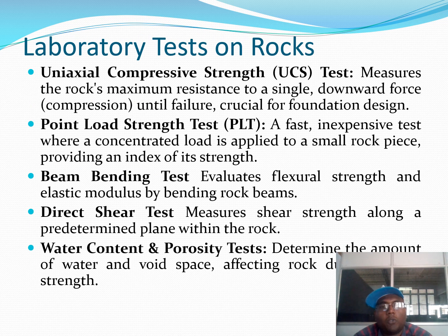Next we see the laboratory tests on rock. UCS test. UCS means uniaxial compressive strength. It is used to measure the rock's maximum resistance to a single downward force. This downward force is named compression, applied until failure takes place. It is used for foundation design.